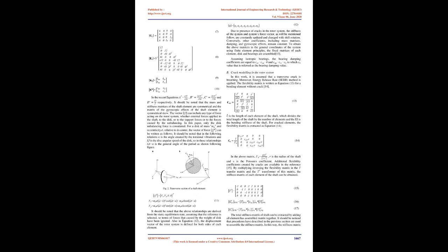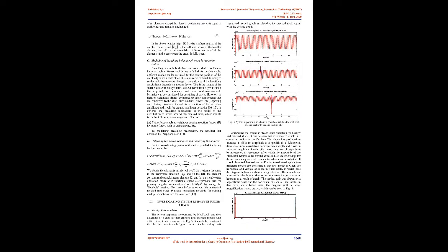2. Rotor bearing system modeling. A. Healthy shaft elements, bearings, and disks modeling. The equation of motion for a rotor system like that shown in Fig 1 can be introduced as Equation 1: M q'' + Ω G q' + K q = Q.